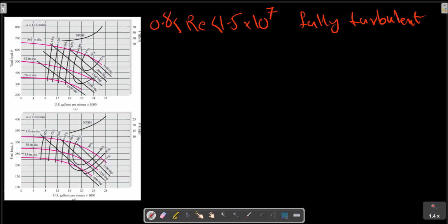For all pumps, the roughness is not given and varies greatly among commercial pumps, but at such Reynolds numbers we expect more or less the same percentage effect on all these pumps.